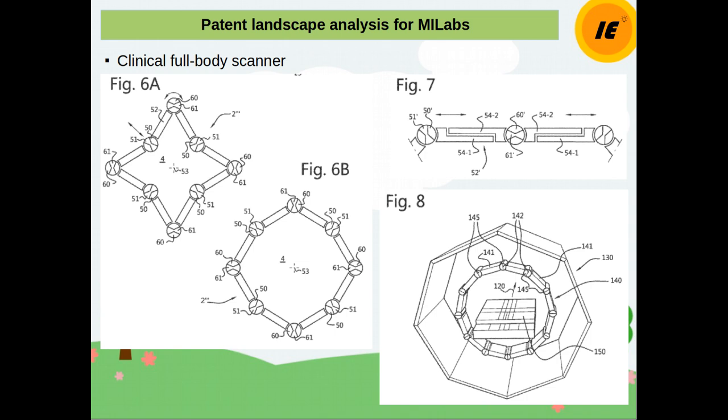And overall, how do you fit this into the overall design, because it's a clinical scanner, so it's a huge design, and generally this collimator has to be made with a very high Z material, because otherwise the radiation will penetrate and you'll lose the purpose of imaging, because of edge penetration. So it will be very heavy, and you need to give it some mechanical structure, so it's a big question here.